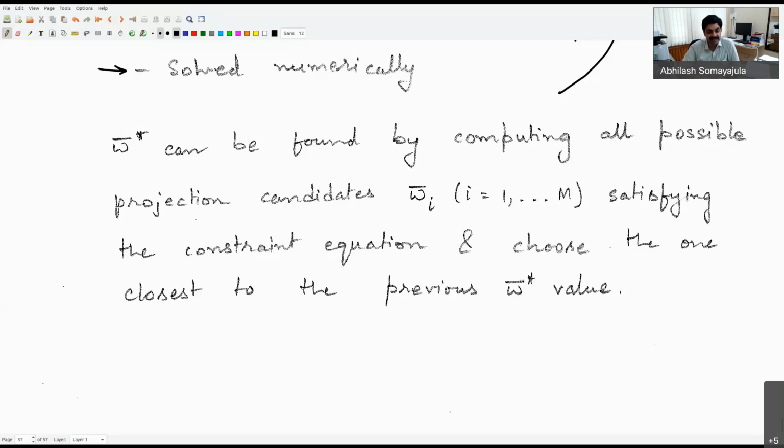Then we looked at the enclosure based LOS scheme, and we understood that the proportional LOS scheme is better because the enclosure based scheme requires us to choose a radius big enough so that the circle actually intersects the line connecting the 2 waypoints. Only then can we find a guidance value.